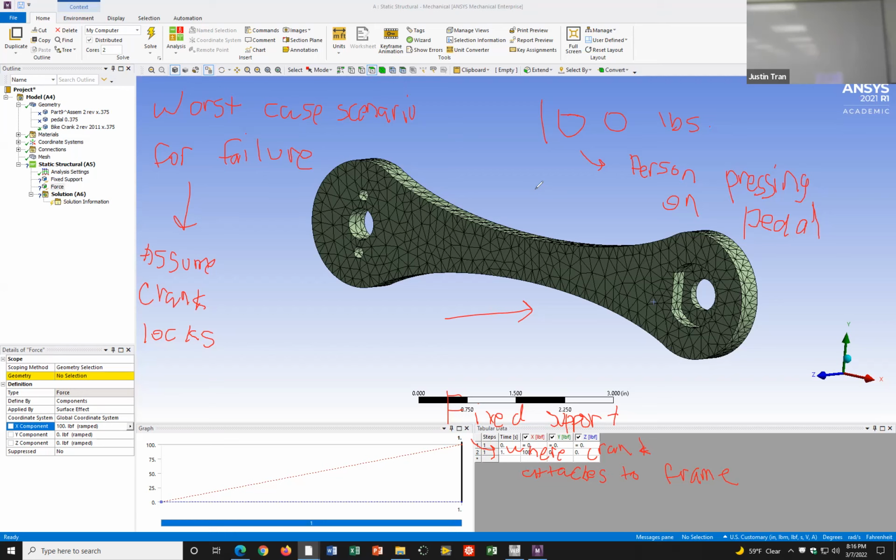I think for this one it doesn't matter because it's a beam, so there's no deformation in this direction anywhere, because the load's only in that direction. For a beam, the roller is effectively the same thing as a pin support if they're going to prevent any deformation.